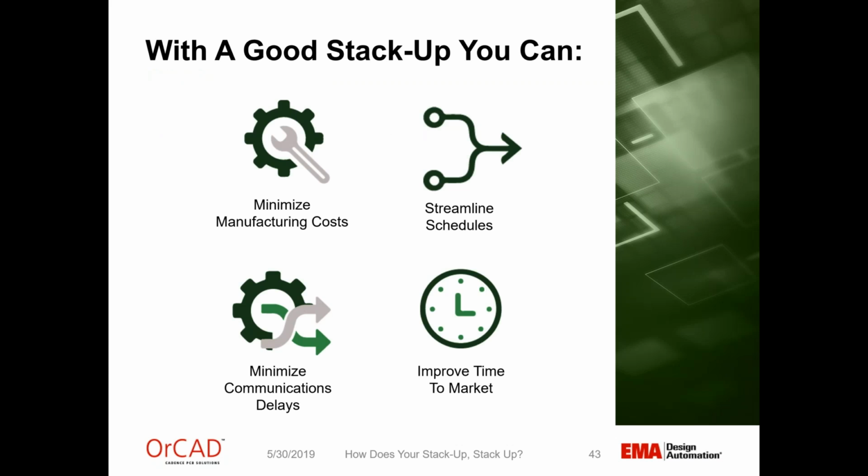So just to summarize some of the things that we talked about today, with a good stack-up, we can minimize our manufacturing, what's going to cost money, what's necessary, what might not be, and figure out what additional add-ons we would like to use to get the behavior that we want in our board. We can find out and streamline schedules and make sure that we're talking to our board house early, make sure we have communication with them in place so that we can see the materials are all going to be available and time is going to be set aside for them to work on our designs. We want to minimize those communication delays and ultimately improve time to market, make sure our product arrives on time.